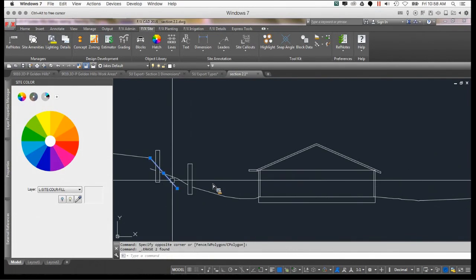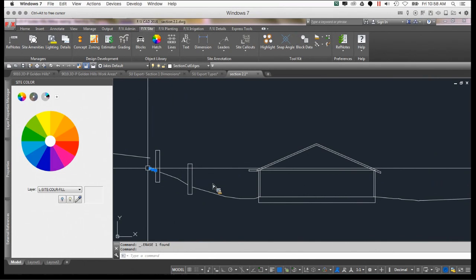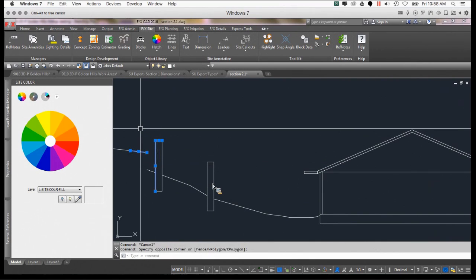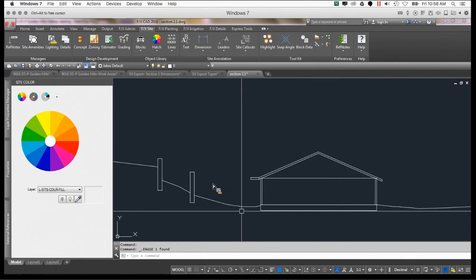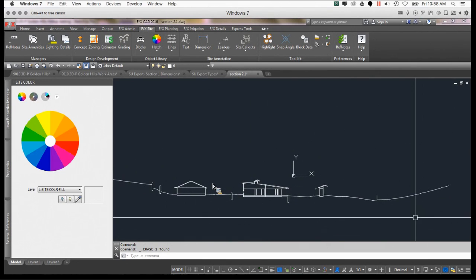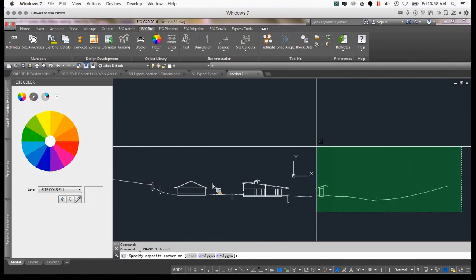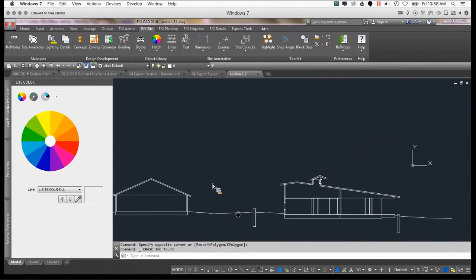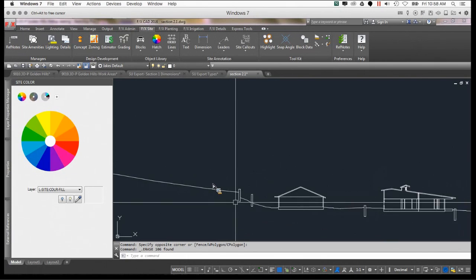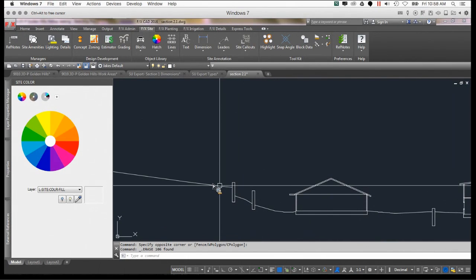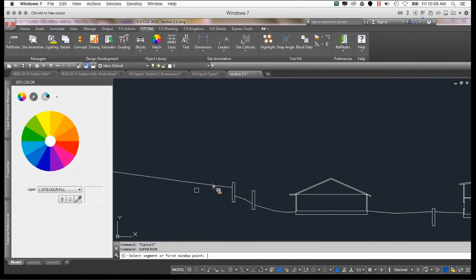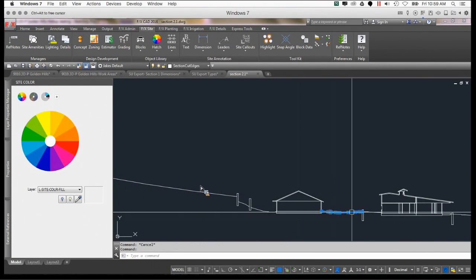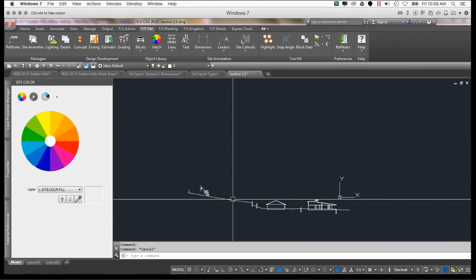And yes, now we go in here and we do a little bit of cleanup. Whatever that would take, I can go ahead and run AutoCAD commands to trim out stuff or add stuff. Again, stopping where we want to with everything, we'll call it that we only wanted to really cut through to there. So I already have my section elevation line work now. What again is really nice is I can run the Land F/X tool super join to click on a line to stitch everything together wherever it can, so that at least I have some full lines that I can do stuff to.